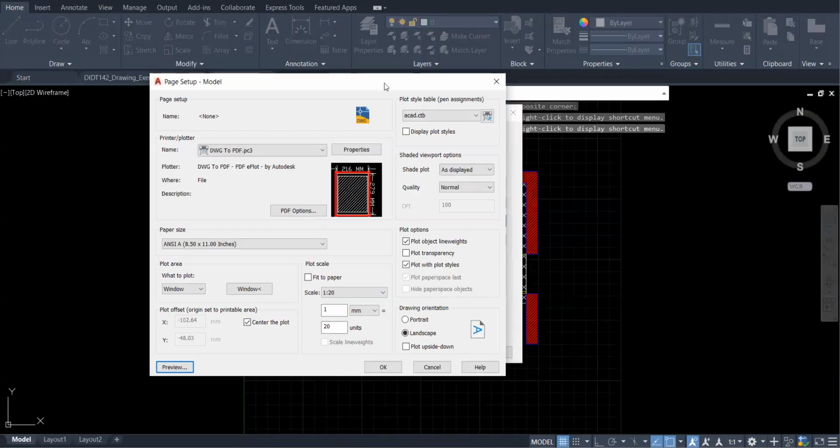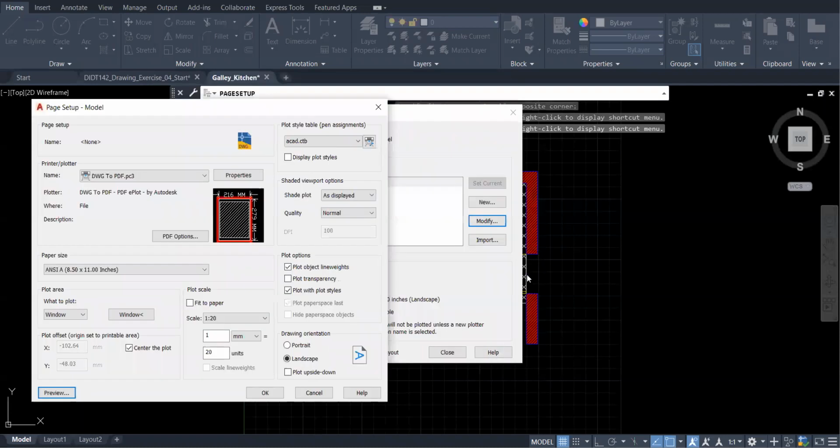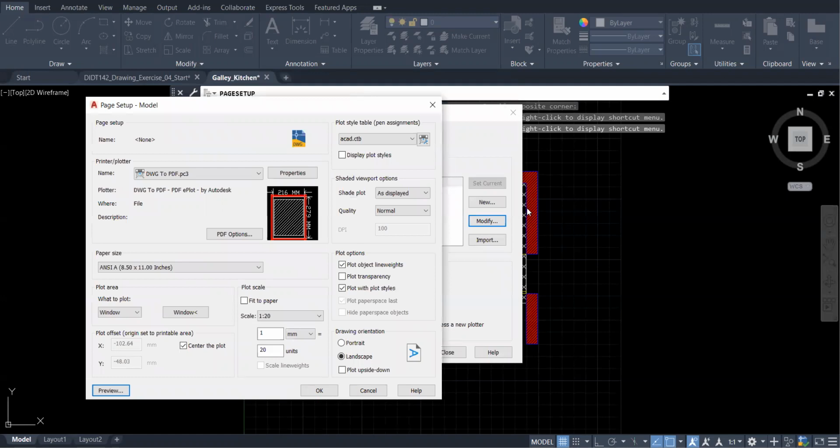Okay, and you might ask, why is there a part here where the tile that we created is not displayed? It's because it's on the 0 layer. Whatever is on the 0 layer is not going to be displayed. So that's why. If you want it to be displayed, you can move it into another layer, or you can totally remove it. I just showed you ways to do hatching with it.